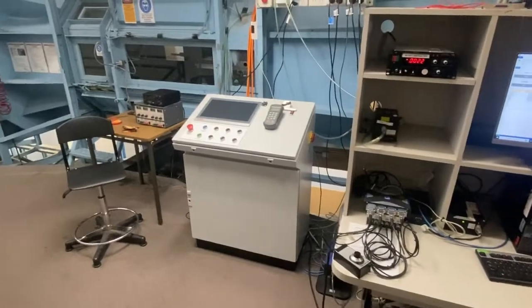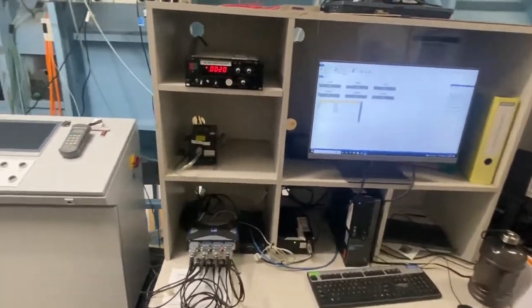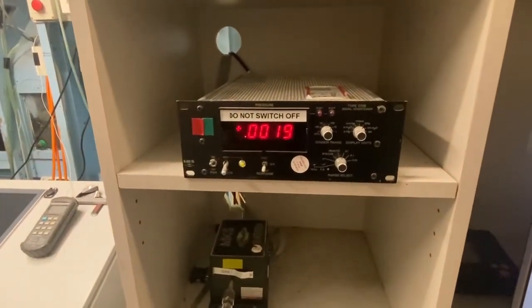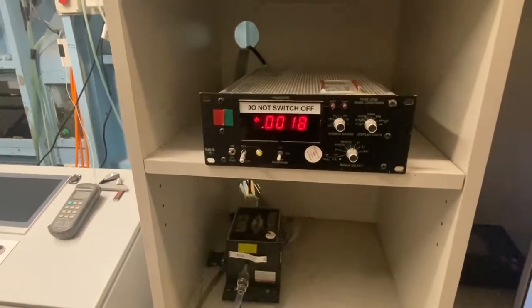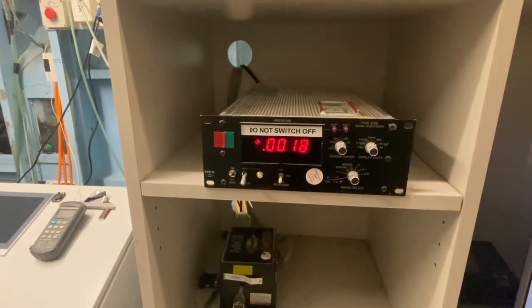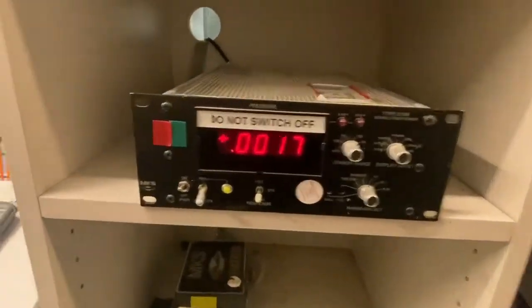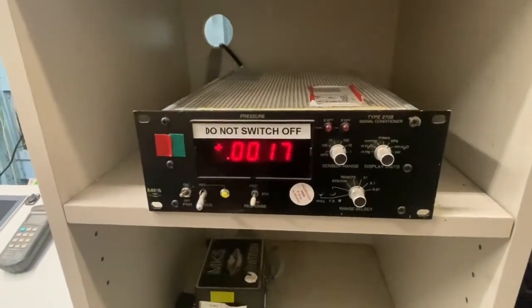Once the force balance has been calibrated and you're ready to begin, we need to find what dynamic pressure we'll be operating at. The way we find this is by the airspeed you've chosen to operate at. For example here, we're going to take 10 meters per second. Using the dynamic pressure formula, we find that the dynamic pressure is 0.061 kilopascals. So we need to ensure that we reach this target on the pressure indicator. Slowly increase the dial until we reach that pressure.